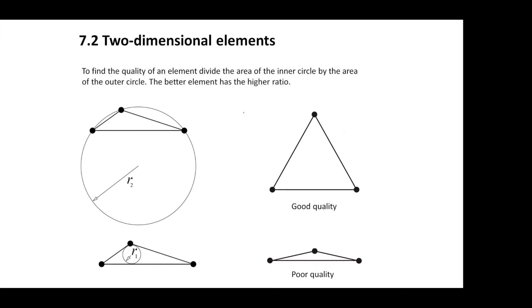One note about the quality of the elements. If we are talking about the one-dimensional elements, this is different, because in one-dimensional elements, you don't have any quality, so to speak. So you have elements small or big, it doesn't really matter. You just change their length. Whereas in 2 dimensions, the quality of the elements would change.